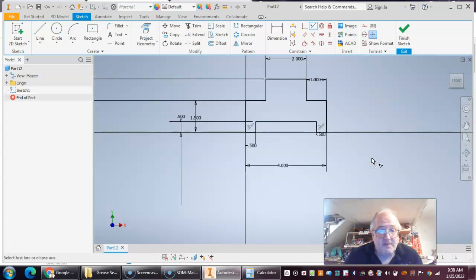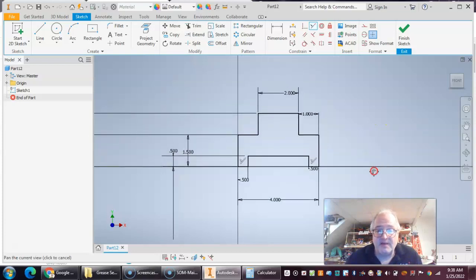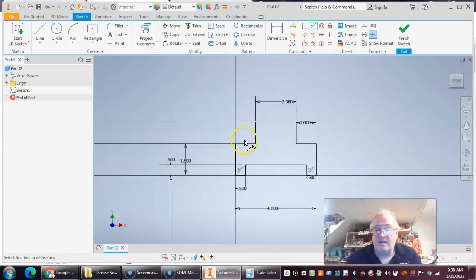And for the most part, our drawing is just about done. So we have placed, as I talked about in class, dimensional constraints. We've got dimensions of size, and we've also got dimensions of location. So each of these line lengths here has size, but of course where this comes into that is also going to be a location. And in this case, whatever that dimension was, it's located a 1/2 inch off of that origin point where we drew it.